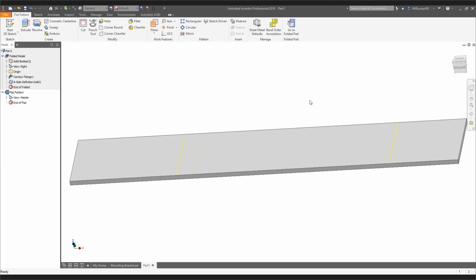And then just to follow up, can Inventor assign a bend radius based on the angle of the bend? Set up as parameters. That's the only way I can think of to do it off the top of my head. That's the first thing I would try. If it gets more sophisticated, like if the bend radius for some strange reason is not a linear relationship to your bend angle, then you may have to look at something more sophisticated, like an Inventor macro using VBA, or iLogic. Actually, iLogic is probably the way I would do it.